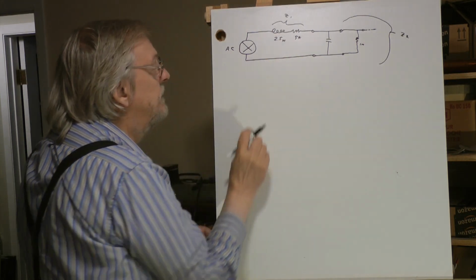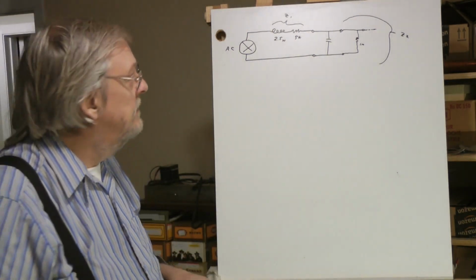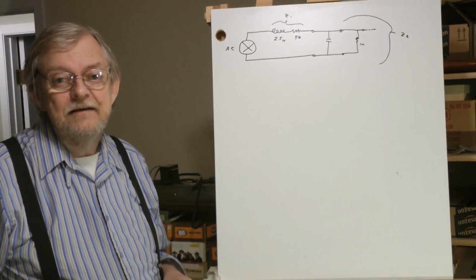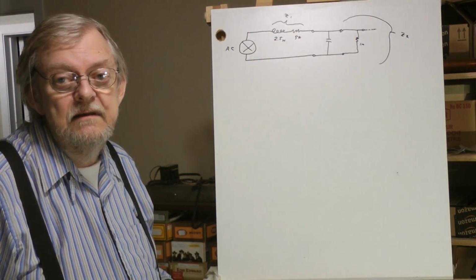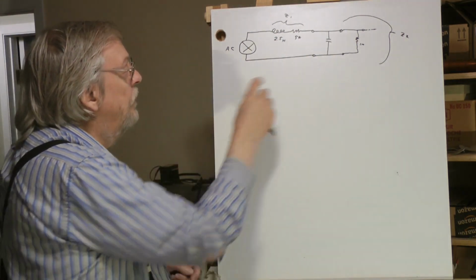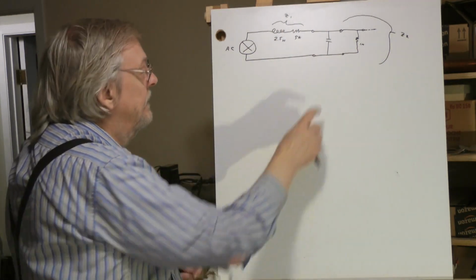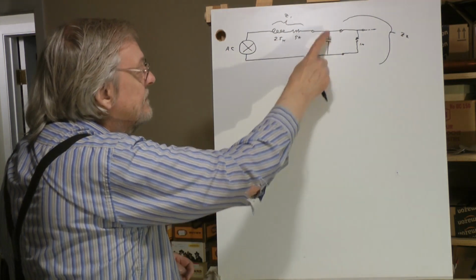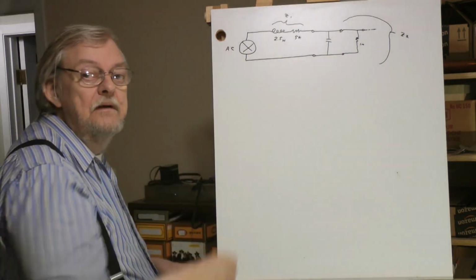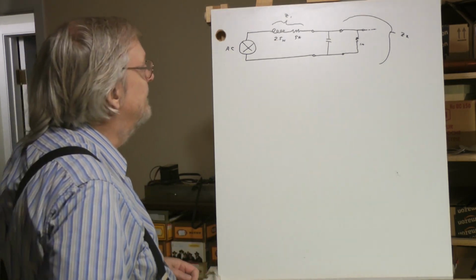2.5 henries. You coil up your guitar cable, you might get a couple of microhenries. If you have a really bright flashlight and take it out in noonday sun, you won't even see it because the sun is so bright. It's the same thing here. 0.1 ohm, you're not going to see it with a 1 megohm load. You get a couple of microhenries of inductance in your cable, you're going to see it against 2.5 henries over here. It's not how the world works, boy.